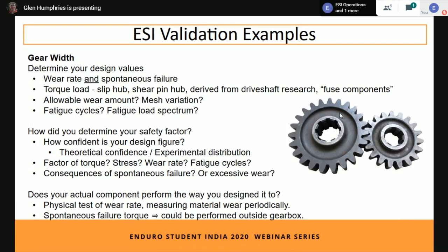At least then you don't need to actually take the gears off the shaft, but you're still taking the thing apart. So that's that friction hub we were talking about earlier, where a certain precise amount of friction holds it onto the shaft, and then we can measure afterwards what clamping levels led to what amounts of torque, and therefore we can see when it was slipping in operation.